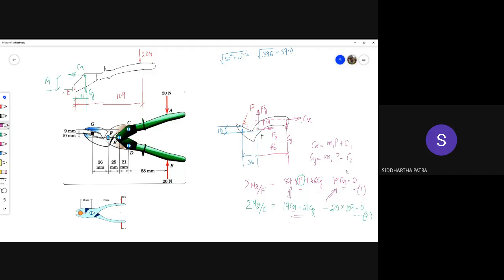I know you are smart enough to figure that out. Is it okay that we can assume that we can have the expressions in terms of P? Yes, sir. Okay. So that means now in this configuration, let's say this is our body number 1, this is our body number 2. In body number 1, we have used how many equations of equilibrium? 1, right? We have taken the moment equation of equilibrium with respect to F. So we have already used up one equation of equilibrium.